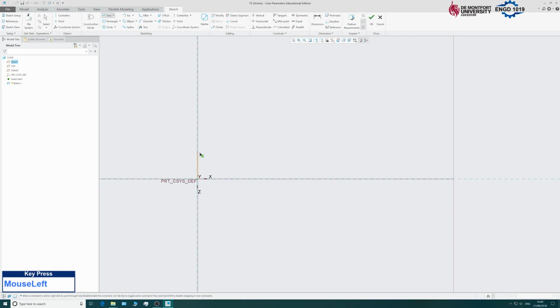And so because this is a revolved part, what we actually need is half of the shape. So you see all of the heights when I input the dimensions will be half that's actually shown on the drawing. Okay, and also when we revolve we need to make sure that we have a completed outline.